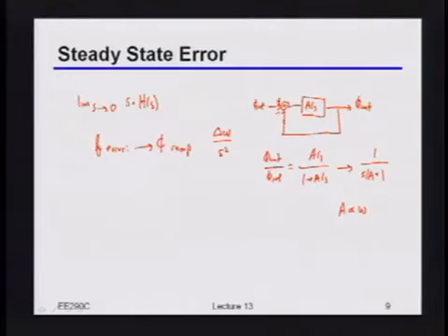At the end of the day, what we're interested in is how big of a phase error we have. So we're interested in phi out minus phi ref. To make things easier, I'm going to assume that phi out over phi ref is something like 1 over 1 plus s over omega bandwidth.